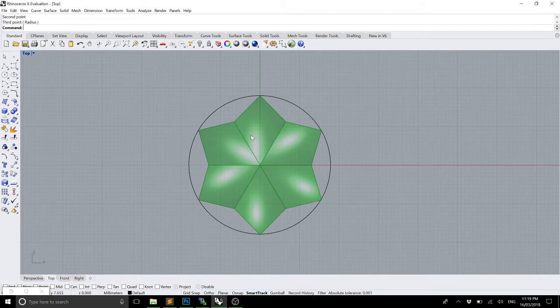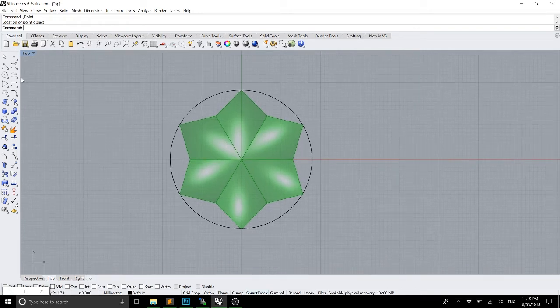I just drew a circle with 3 points, but I think what we might want to do is define a center point for our circle, and then we can define a circle from a center point and then a radius. So in this case, it looks like the radius is 18, but this will be a variable in our script. So there's a second circle, and this time I'm going to draw it from that point, and that defines the inner set out for these kite-shaped diamonds.